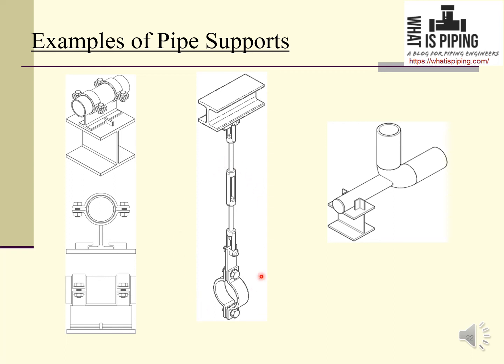Now this is an example of rigid hanger. So the pipe will be clamped with this clamp, and it will be hanged from an overhead structure. Now this is an example of trunnion support from elbow in horizontal direction, which is guided. So all these are called guide supports on trunnion. The guide members are also considered as primary supports, even though these are not normally welded with the piping element. Only the secondary structures at bottom of these are secondary supports.